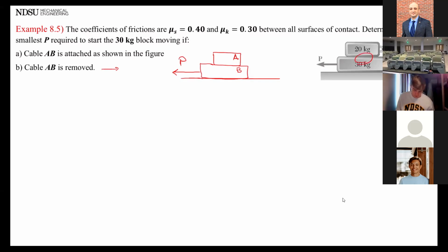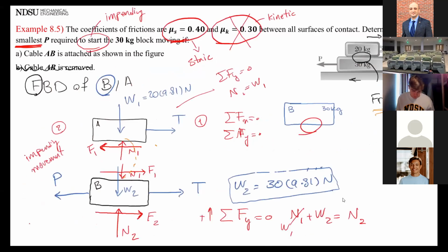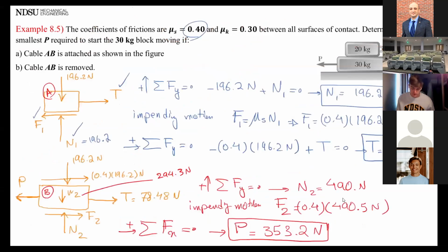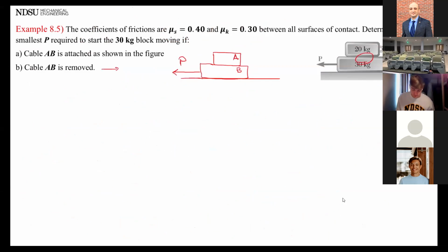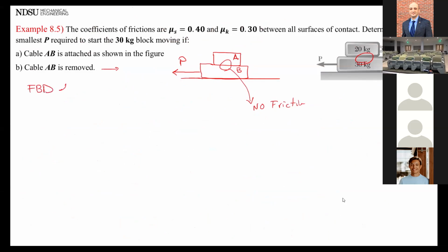But right now, I also mentioned another reason here. Remember? I said that the surface between those two has friction. Right now, is there going to be friction here or no? Between the two blocks. No, because there's no force acting on A. Yeah, so A and B are going to just move together, right? So no friction at all between the surface. So I can just draw a free body diagram of AB kind of together, glued together, as one block.